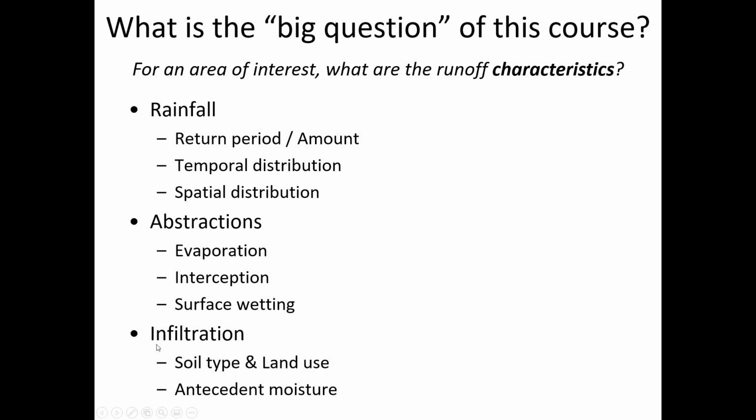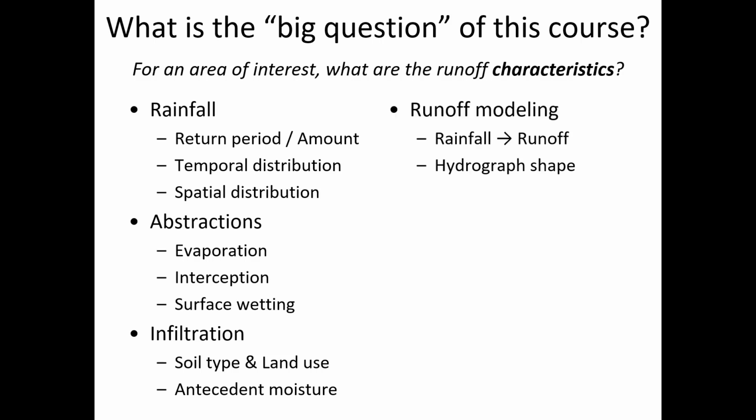Now, infiltration, of course, the two methods we talked about were Green-Ampt and then the Horton method. And these are ways to estimate the declining potential rate of infiltration and how the suction head decreases as the pores begin to fill during an infiltration event.